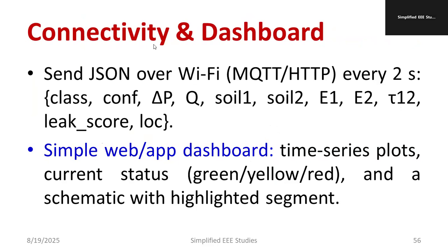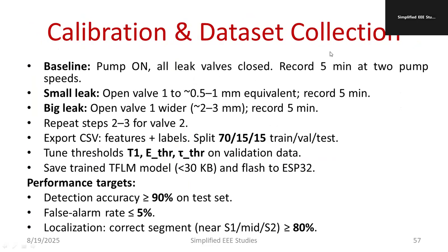You have to set up the connectivity and dashboard for better visibility of what exactly is happening. We are going to enable the dashboard. Then calibration and dataset collection, like a baseline: run with the pump on and all leak valves closed. Record different conditions, but initially you have to make everything closed and make it healthy.